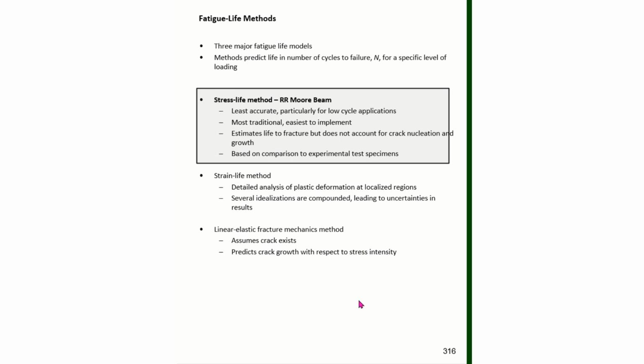We want to now look at the various theories and approaches to solving fatigue problems. There are three major fatigue life models, and these are the methods that predict the life in number of cycles to failure for specific loading. And the three fatigue life models are the stress life method, the strain life method, and the linear elastic fracture mechanics method. And I'll expect you to be able to identify the three and talk about them a